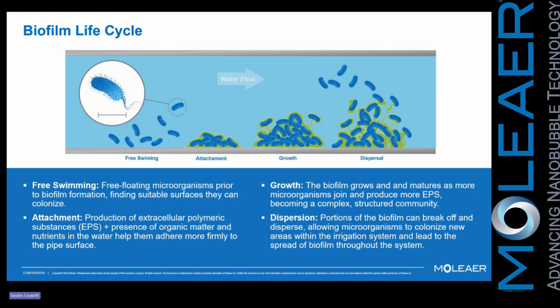And then as they develop, there's this growth stage. This is when we start to get into some real trouble. This is when the biofilm grows and matures. There are more microorganisms joining. They produce even thicker amounts of this EPS or bioslime, becoming a really complex structured community. From that stage, it becomes very difficult to manage. The EPS, that bioslime they produce, is largely protecting these microorganisms underneath, and it's very difficult to manage biofilm aggressively when you're in this growth stage.